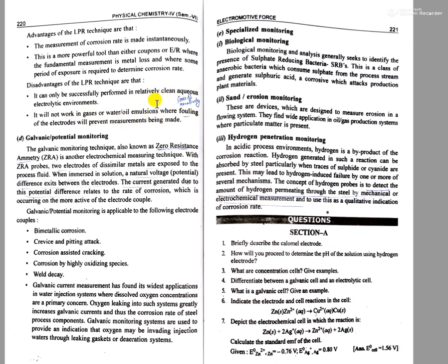Fouling means the loss of sensitivity of that electrode surface. In such cases, this technique will not work. So extreme sensitivity is required for this LPR technique. It can be performed only in clean aqueous electrolytic environments.